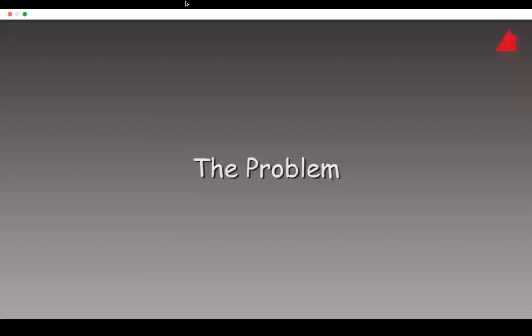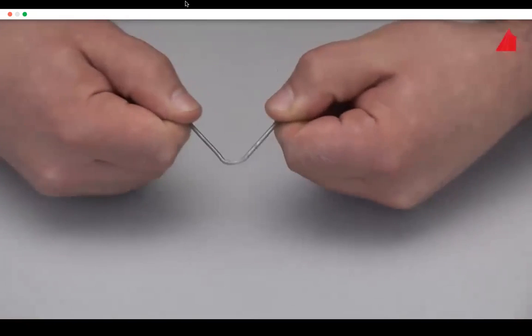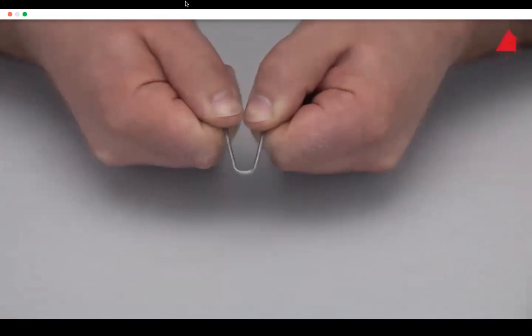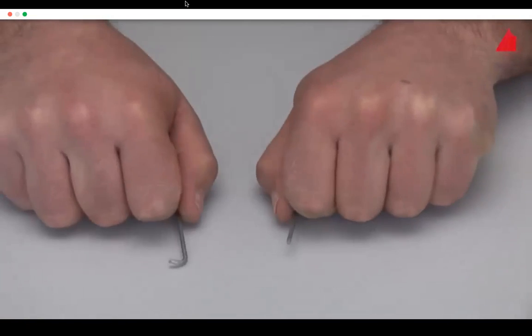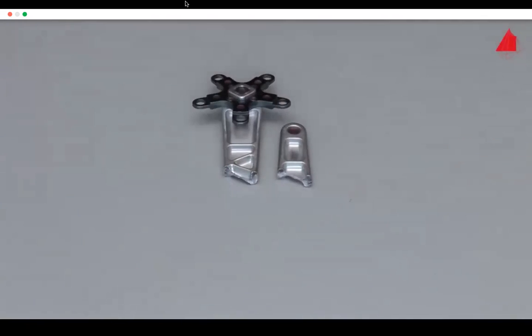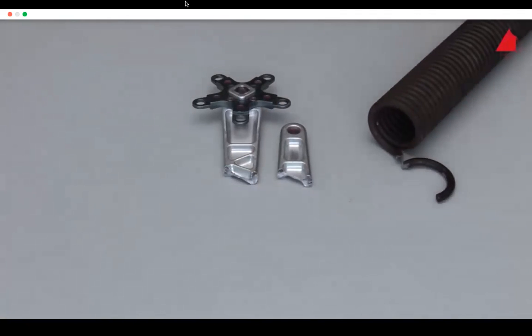The problem with materials is that they normally endure less under repeated loading than under a once-only load. The wire does not break when first bent, but bending it back and forth repeatedly leads to an early fracture. This bicycle crank arm had only been able to endure the cyclic loading for a certain time before it broke. The fate of the garage door spring was the same. It had borne the opening and closing of the garage door about 60,000 times before it finally fractured.